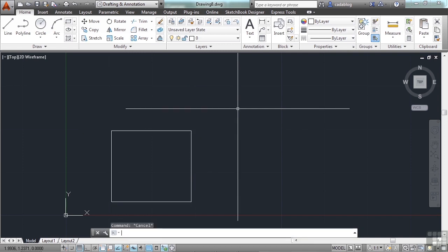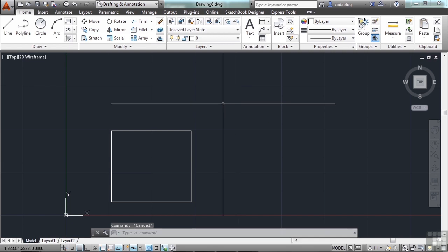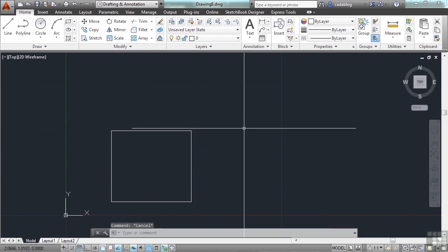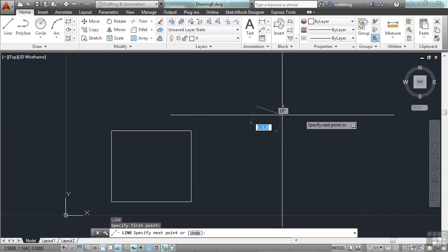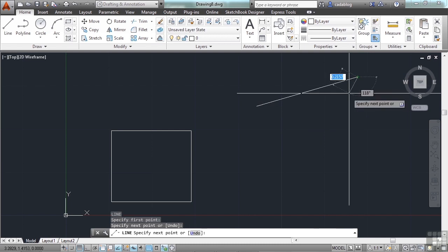The number on the left, as with most standard Cartesian coordinate systems, is the value of the point on the x-axis, or the horizontal axis in this case. The number in the center is of the y-axis, or the vertical axis here. And then the third value is the z-axis. As you can see, as I move around this plane, and in AutoCAD LT, it's at 0. So let's draw some lines and find their coordinates. Just start in a blank file and draw a line. Type in L for line, and then pick a point anywhere, and then draw it to somewhere else and press enter.